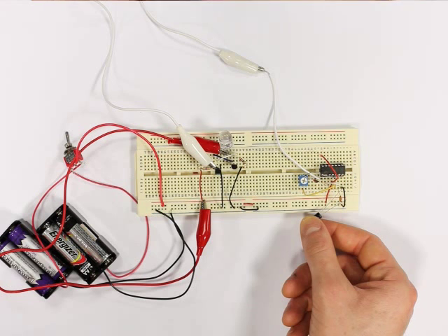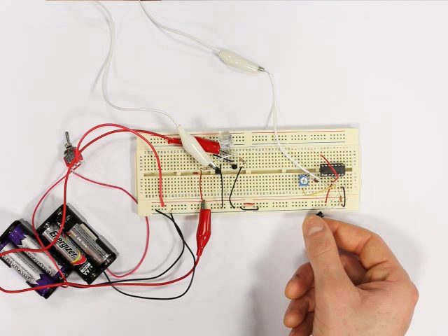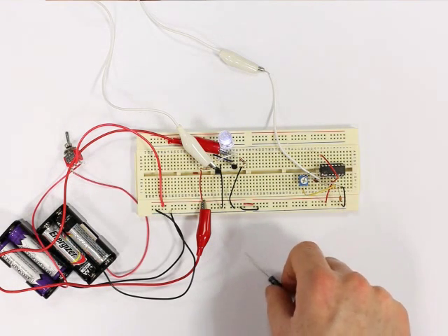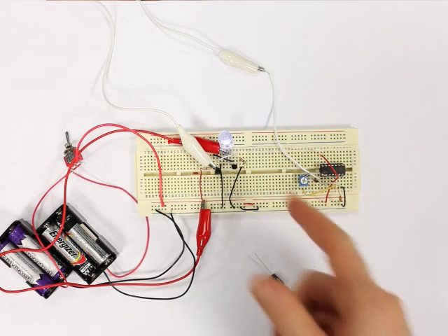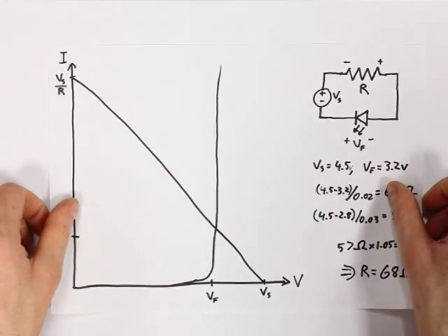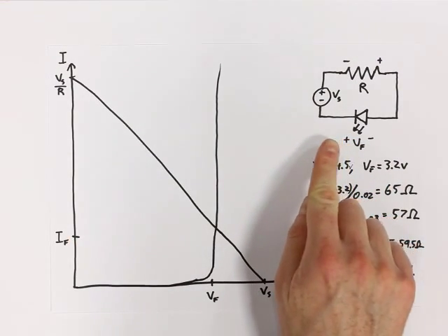There we go. So you can see there it's only a very brief pulse of light with a longer off period. And the frequency also appears to have slightly increased, as will happen when you change the resistance. So there you go. That's our pulse width modulation circuit for effectively plugging it straight into a constant current driver for an LED.